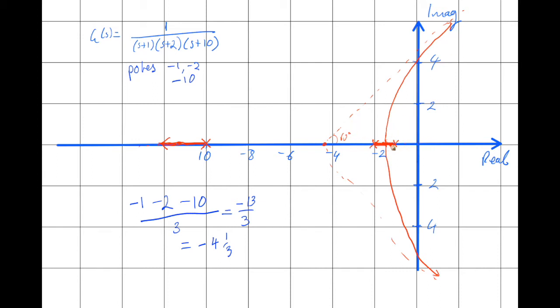if you were to consider tuning the gain, we're going to see a slight decrease in settling time as you increase the gain, but then as you increase the gain further, the settling time is going to get worse. The real part is getting closer to the imaginary axis here. I mean, the real part is getting smaller, the root locus is getting closer to the imaginary axis. The overshoot is getting worse, so as we go up here, the angle from the real axis is getting larger, but the rise time is getting better.